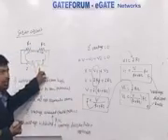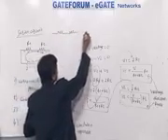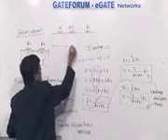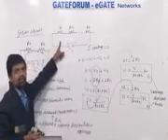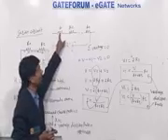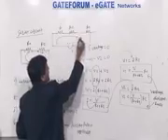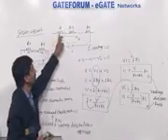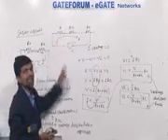Whenever I have connected n number of resistors in series like this, Rn, R2, R1, V, then also voltage division rule is applicable. That is, voltage across any element is equal to total voltage into same resistor value divided by sum of resistors, and current flowing through all these elements remains same. Current which is entering at any point is treated as positive. This is sign convention. Current which is leaving at this point is treated as a negative, and KVL is applied.